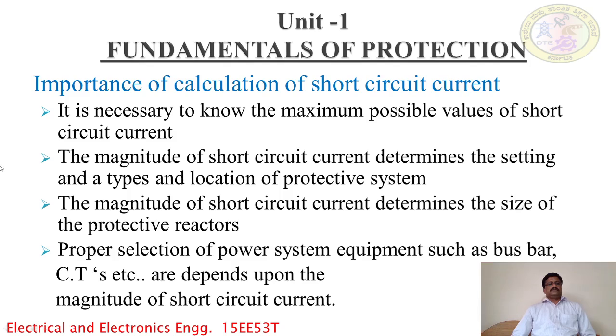So next, a very important topic, the importance of calculation of short circuit current. So first, what is the necessity for calculation of short circuit current? It is necessary to know the maximum possible value of short circuit current in the power system, because the power system has different equipment connected.